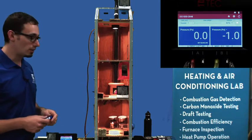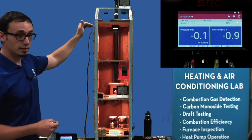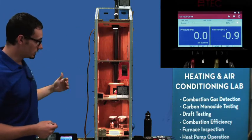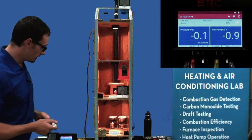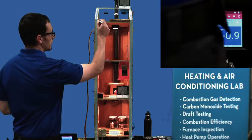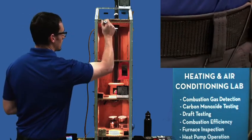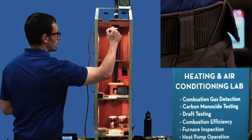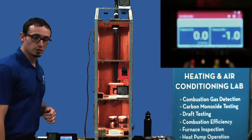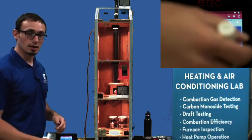So I went from a positive 0.9 on channel A, that's the probe at the top of the building, to a 0, and now my neutral pressure plane is completely shifted. It's completely flipped locations. So now my neutral pressure plane is up here at the top, and anything below that neutral pressure plane is going to be a negative pressure. So the whole building in this scenario is negative.